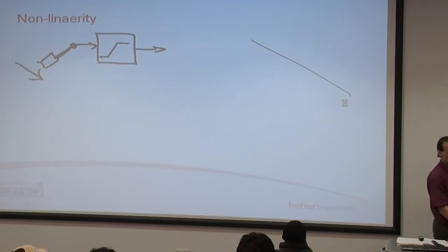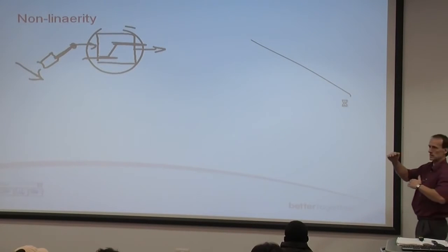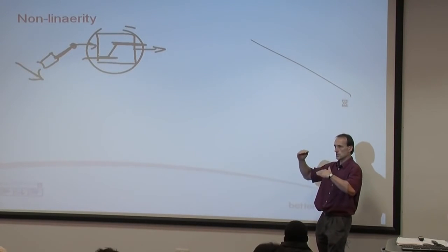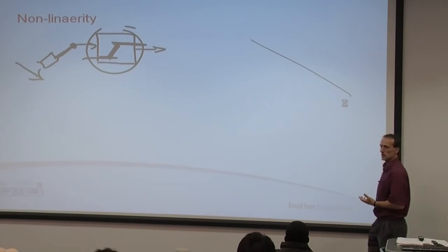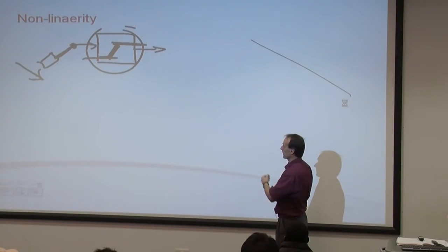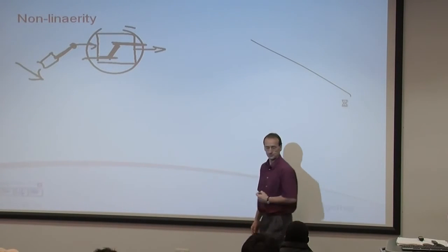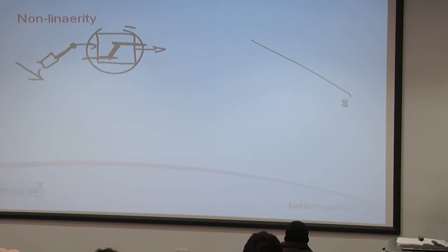In order to represent that in the model, I had to introduce this block which limited the motion of the pedal between 0 and 100%. I think we gave a number of something like 60 millimeters, whatever it was, 100 mil. But in between those two places, its behavior was linear. So even the simplest kind of system, like this cruise control throttle pedal, to model it properly, we can see that it is non-linear. I won't start talking about the engine, which is also not linear, but we'll just forget that one for now.